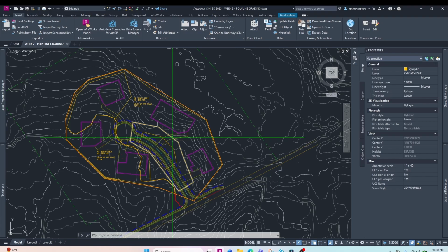And when you redo a lot of the feature line and the automation tools, AutoCAD gets really slow and starts bugging out. Most of the time when I have a grading plan that has a lot of feature lines and a lot of grading groups, the surface starts eating itself. It starts having gaps. It starts messing up my contours.